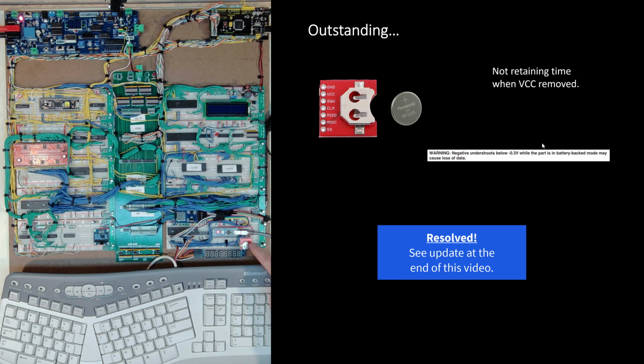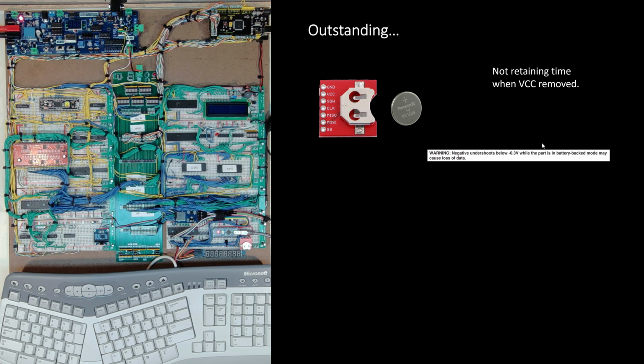So I did also order an additional one of these, a slightly different model, but pretty close to the same thing, that I can use just to test and see if there's something actually with this design. I need to go back and scrub the data sheet too and see if there's something I'm missing, but maybe there's a configuration I have to tell it to go ahead and actually use battery to retain time of day, but I wasn't seeing anything anywhere that indicated that so far. So that's my outstanding issue that I've got to go ahead and work on.